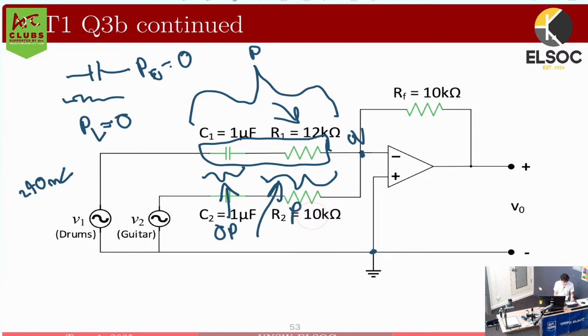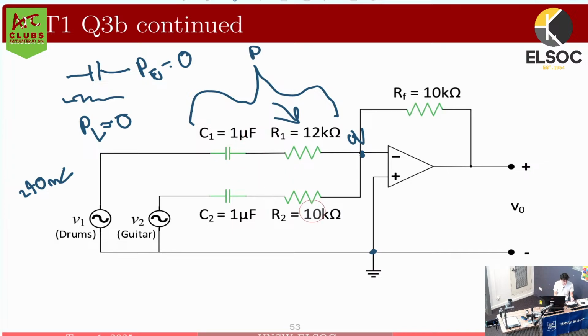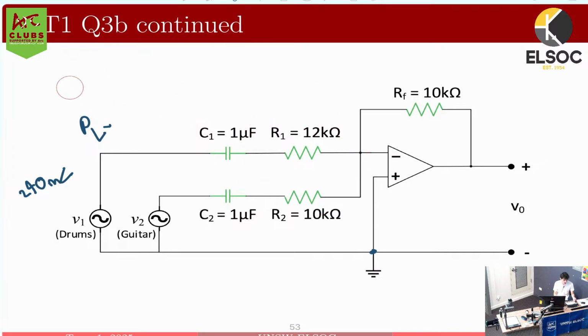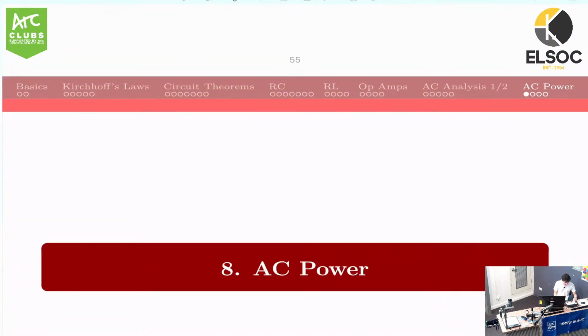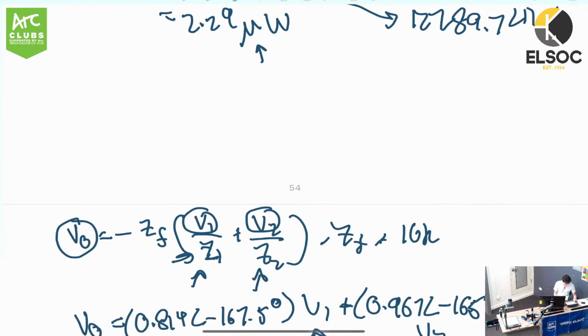And that'll actually make things pretty quick if in the exam you're asked a question like, find the power for all of these elements. From the start, you can say, I can see an inductor here, a capacitor here, and another inductor here. Because of that, I know that all of them have an average power of 0. I can just say that. And so that's the end of that problem.